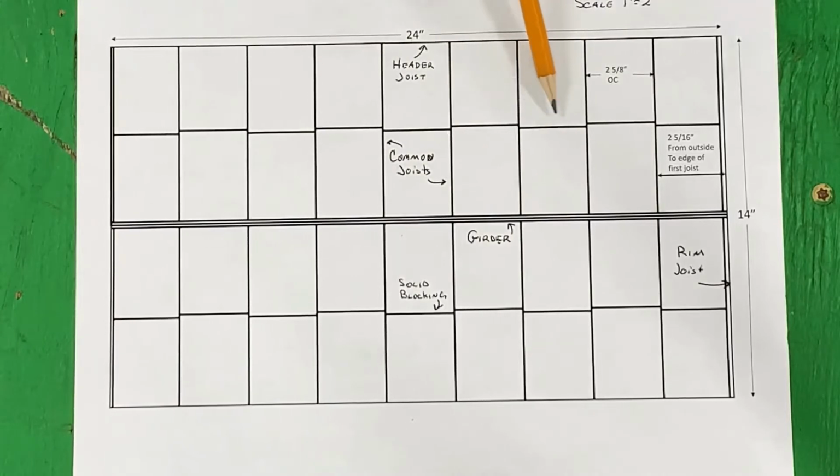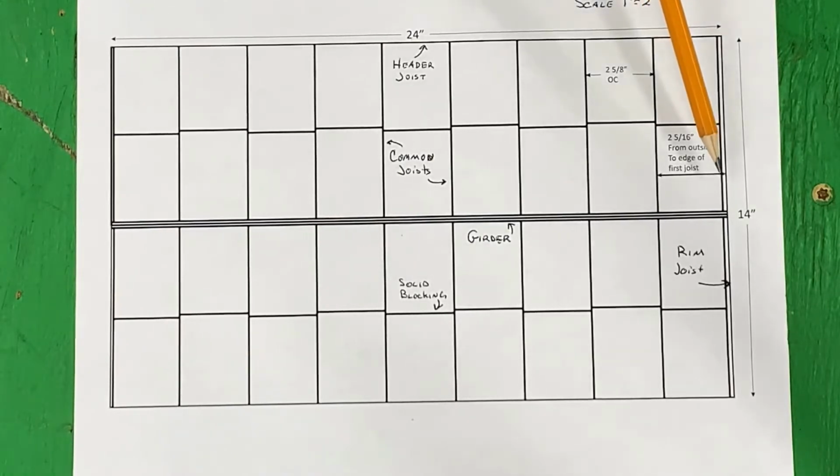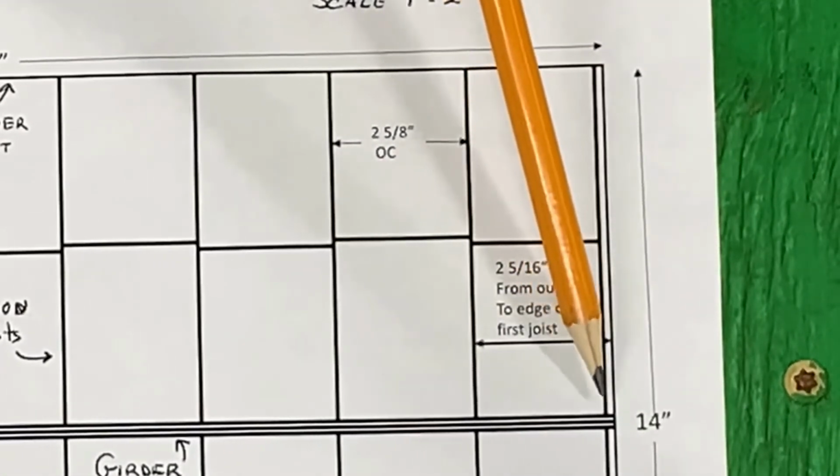And if you notice in this blocking, they're actually offset. And then they too appear to be center across this span, because this common joist is going to span from where it contacts this header joist all the way over to where it connects to the girder. If you look close in detail when you actually look at your paper copy, you see it a little clearer.